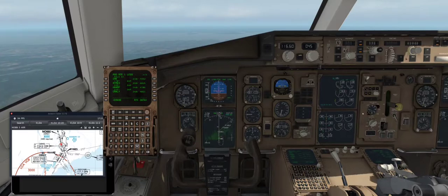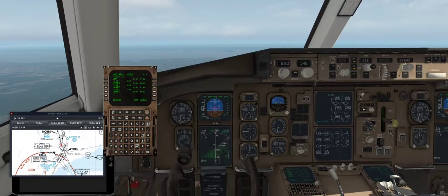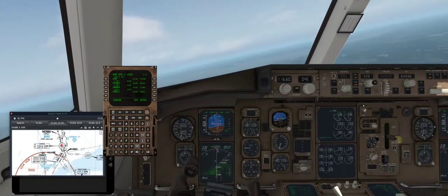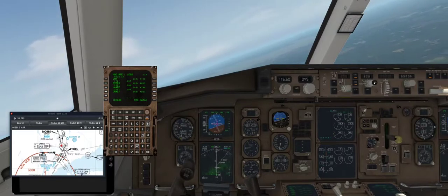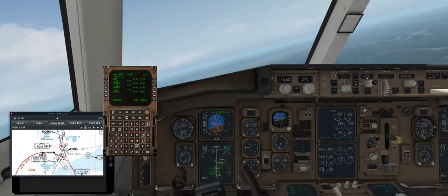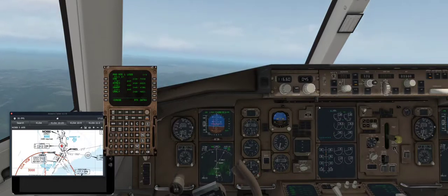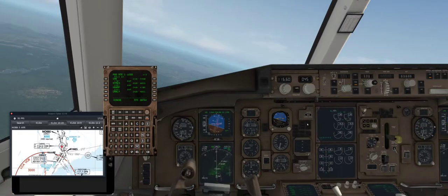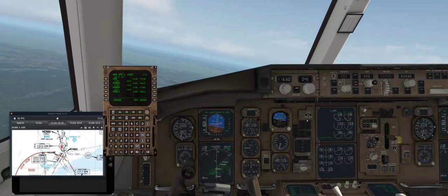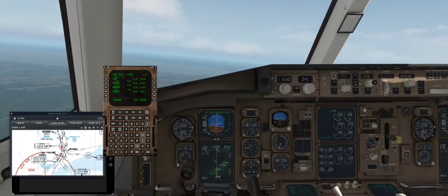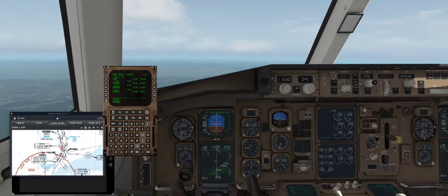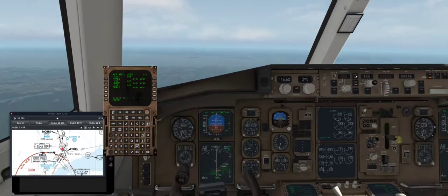Now, as a pilot of this very advanced aircraft, I should know how it works, but I've honestly never played with the hold feature here. And it's going to do another hold. So we're going to override that. Watch, now it's going to continue on 75. And we didn't veer off course for long enough that it should really upset air traffic control too much. And we're going to say direct to Rhymes. So we're going to hit the direct button, hit Rhymes, and then hit this, and then hit exec, and watch. See, now Rhymes is the next point, and now we can go back to LNAV and VNAV mode.